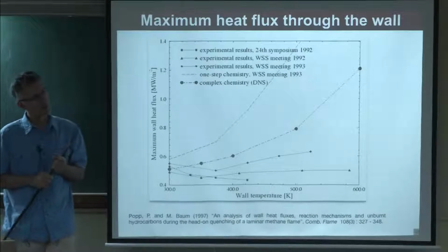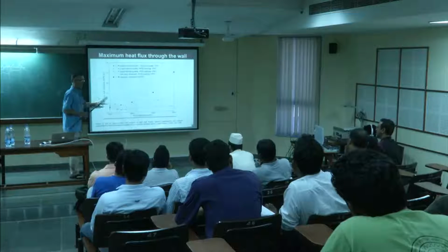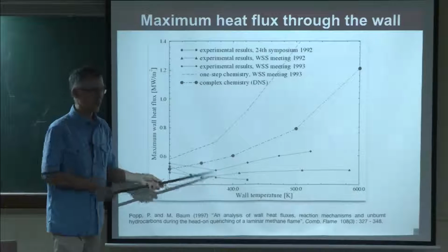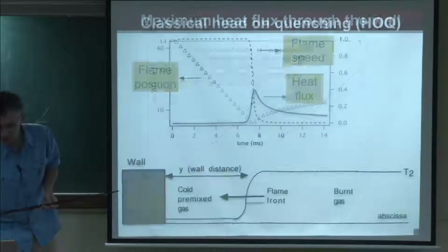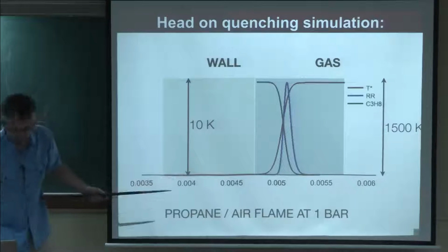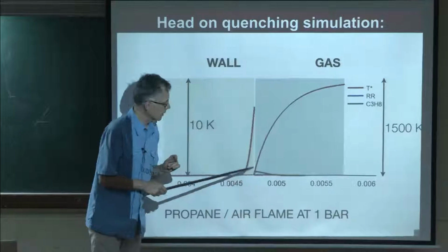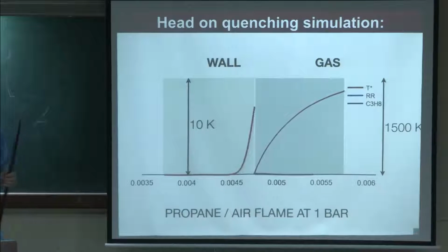What I'm trying to say is that the distance between where the flame quenches and the wall may keep decreasing as you increase the wall temperature, and when the wall actually burns, it actually reaches. Well, those walls don't burn, okay? They're not supposed to burn. It's too cold yet. 400K, they're not going to burn. They're going to go from 300 to 310K, as you can see here in the movie. And so that's not enough to have the wall burn. It's only influencing chemistry here. In the wall, there's no combustion. Should not be. Otherwise, we have a major problem.